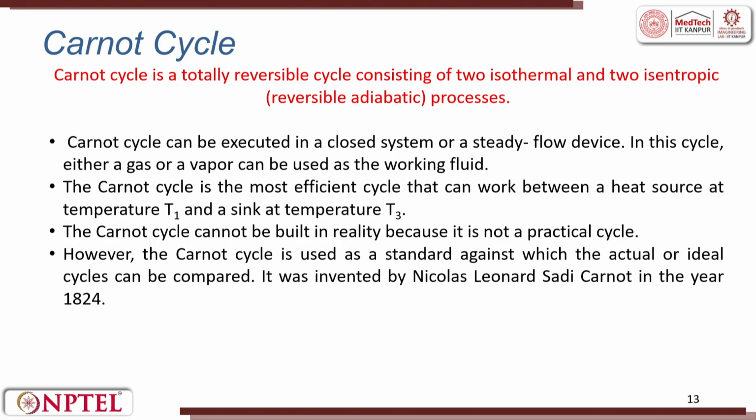Next, let us get into the Carnot cycle. The Carnot cycle is a totally reversible cycle consisting of 2 isothermal and 2 isentropic processes, wherein the isentropic process is always a reversible adiabatic process. The Carnot cycle can be executed in a closed system or a steady flow device. In this cycle, we use either gas or vapor as the working fluid.